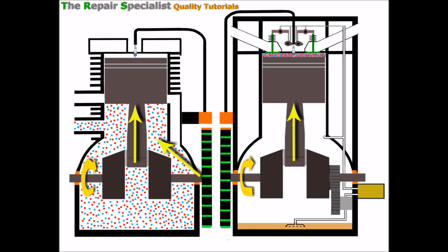And so at this point, that air and fuel is all over the crankcase. So the crankcase is absolutely saturated with that air and fuel mixture. But at this point, when these pistons are at top dead center or near top dead center, these magnets here on the flywheel that we looked at earlier are specifically placed on the flywheel so that when each piston is at or near top dead center, they line up with each coil pack.